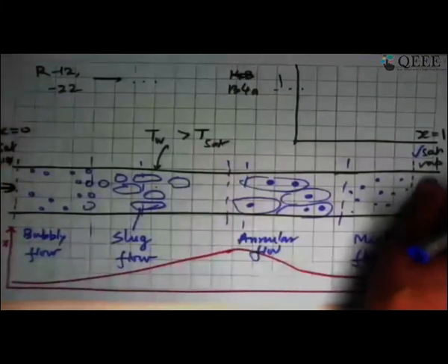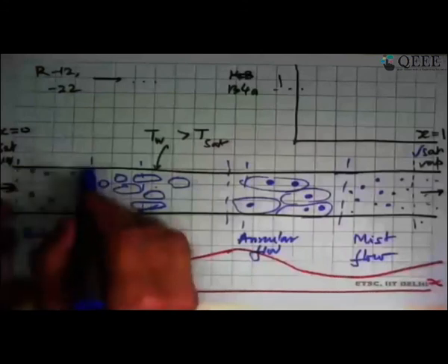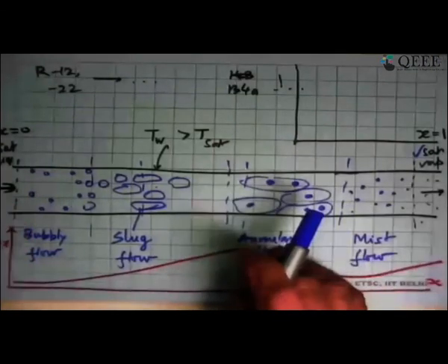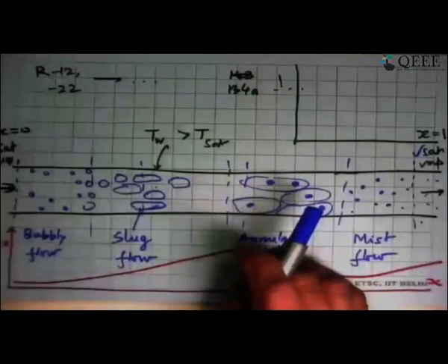Those are all nice and beautiful non-dimensional forms. But how do I tell pressure drop in a bubbly flow? Very difficult. Pressure drop here, pressure drop in this, pressure drop in this. So the only thing to do is to do a lot of experiments, figure out what the pressure drop is at different points, and from there develop some relation that for this material, for this tube, with this roughness, for this temperature, this is the type of pressure drop you get.